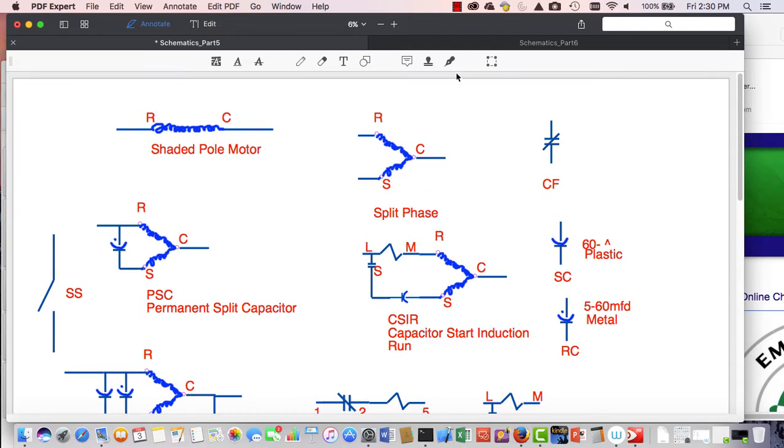So what we're going to start doing is take all these components and start building actual circuits and components and systems that do work. A system, any HVAC system, is just a bunch of components put together to do something. Our ladder schematic allows us to see these components and understand the sequence of operation. A pictorial shows you where they're at and how they're wired. But the ladder schematic shows you the sequence of operation, which from a troubleshooting perspective is the most important part of the process.